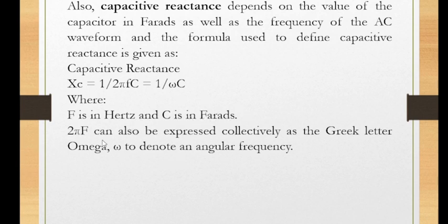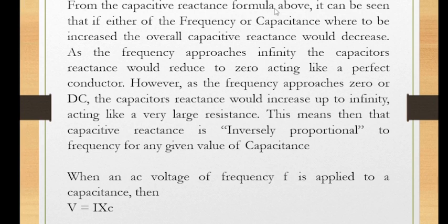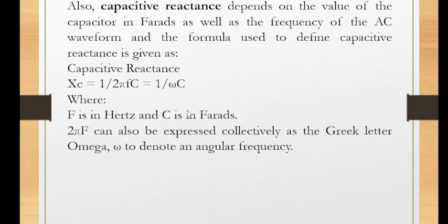Don't forget that 2 pi F can also be expressed collectively as the Greek letter omega to denote an angular frequency. From the capacitive reactance formula above, it can be seen that if either the frequency or the capacitance were to be increased, the overall capacitive reactance will decrease. Why? Let's go back to explain. The capacitive reactance is inversely proportional to 2 pi Fc. So it is inversely proportional to F, the frequency, and also to C.